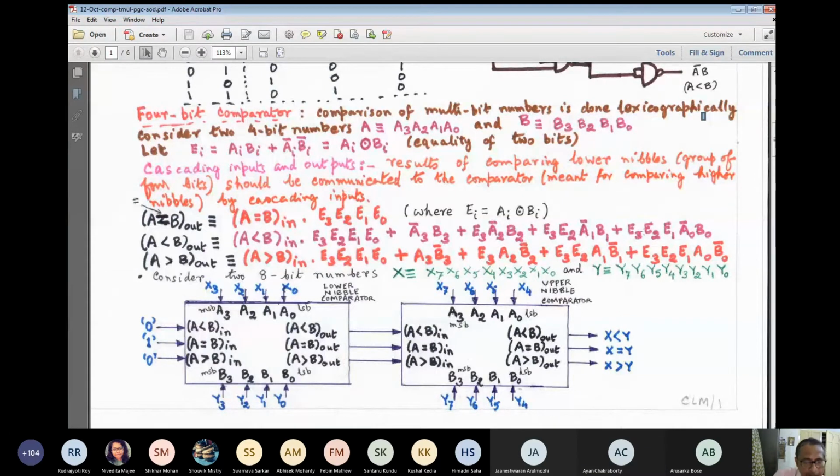How many gates you will need will now be an easy task for you. That is a cakewalk, because you all know how to implement that. I require here 4 twin input equivalence gates, or 4 twin input exclusive NOR gates. Then connect it with this. So I require a 5 input AND gate. That is known to all of you. Here also I require a 5 input NAND gate. Here I require a 2 input AND gate, 3 input AND gate, 4 input AND gate, 5 input AND gate, and finally a 5 input OR gate.